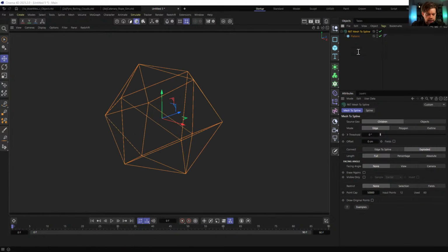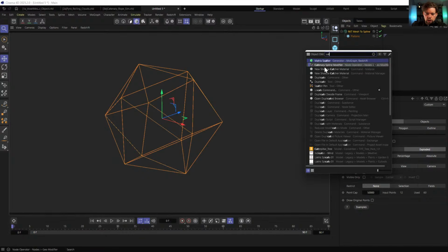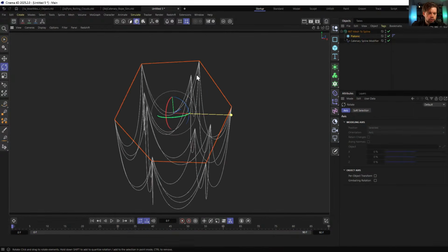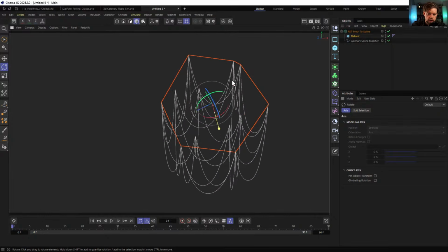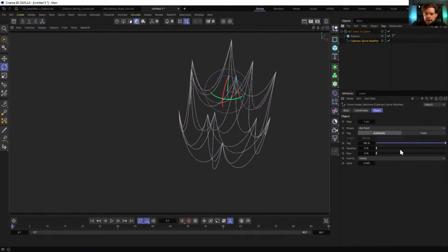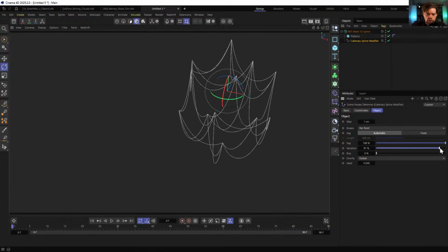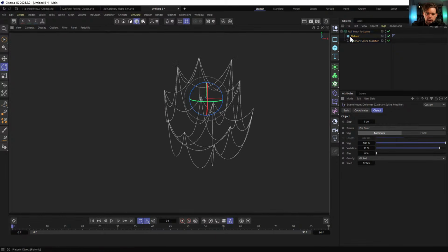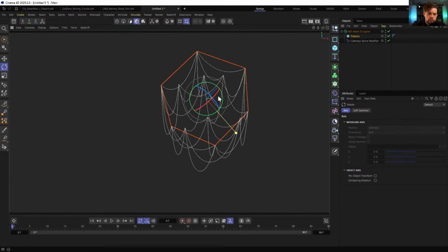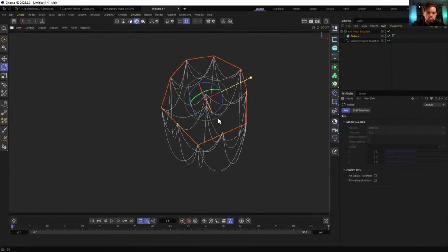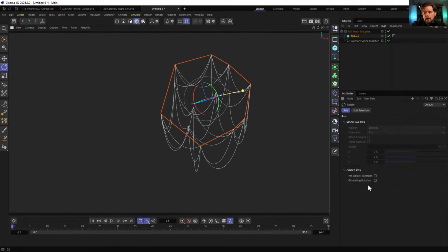And if we make a catenary, so here's another catenary spline modifier. If I drop that on, you see all those lines will droop, which is kind of cool. And if I were to grab the original object and start rotating it, you can see I can spin this around, and those lines will be always updating and drooping down. So that's pretty fun. We could add variations, so some go down further, some go down more. We could put more bias, so there's like heavier contrast, so more small ones, more long ones. And then I can go back and start spinning this around, getting all these kind of dynamically drooping down. Not literally dynamically, but you see automatically they're mathematically drooping down.